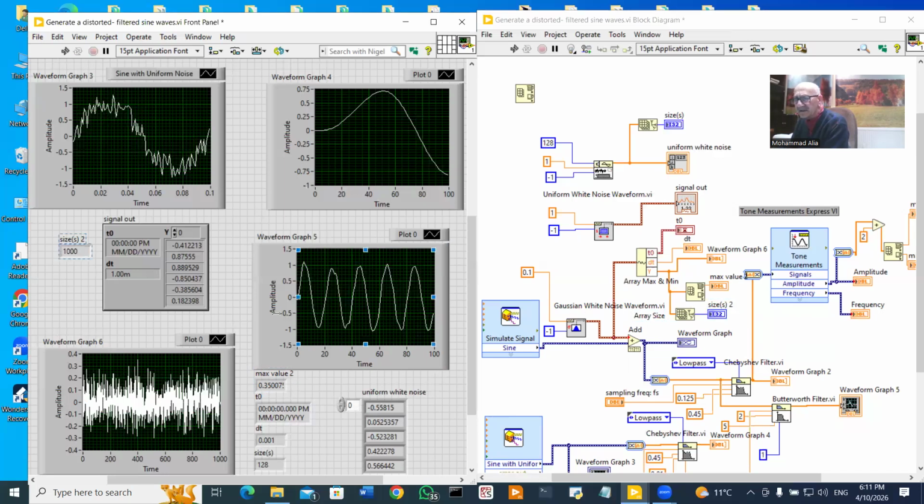If I press it here, yes, it is here 1000. So I have here 1000 number of oscillations of sine waves, each of them, as you see, having a 1 millisecond duration. And the total, of course, will be 1000, as you see here, milliseconds. This information and management is very useful for you when you work with LabVIEW.